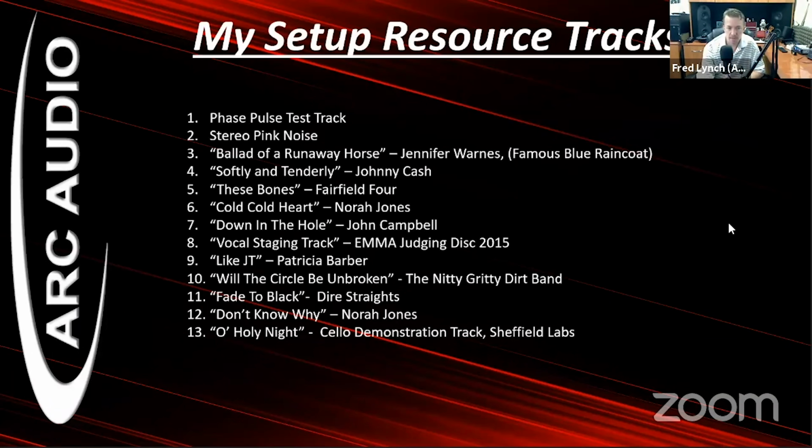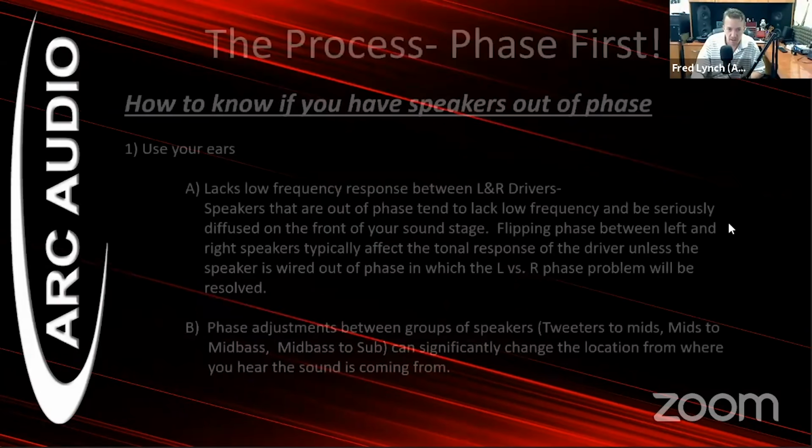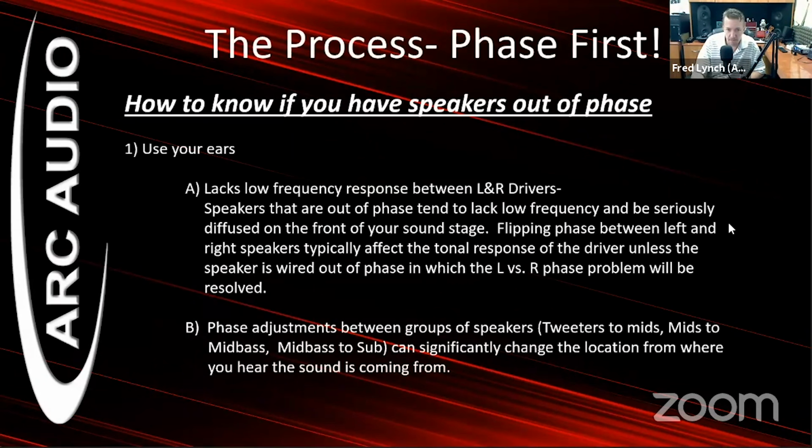We'll post this information later so everybody has it as a reference if they want to go out and acquire the tracks and use it as a reference for this tuning process. So use your ears. How to know if it's out of phase: if it lacks frequency between left and right drivers, especially in mid-bass or even mid-range drivers, it's out of phase.